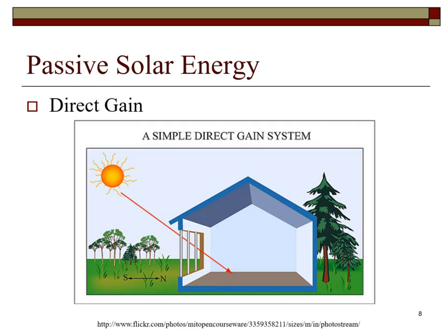This approach works best when the south window area is double glazed and the building has considerable mass in the form of concrete floors and masonry walls, insulated on the outside. The direct gain system will utilize 60 to 75% of the sun's energy striking the windows.